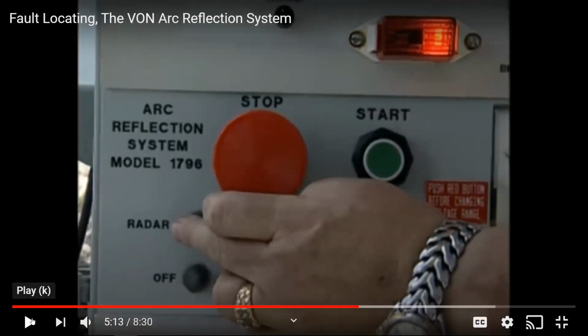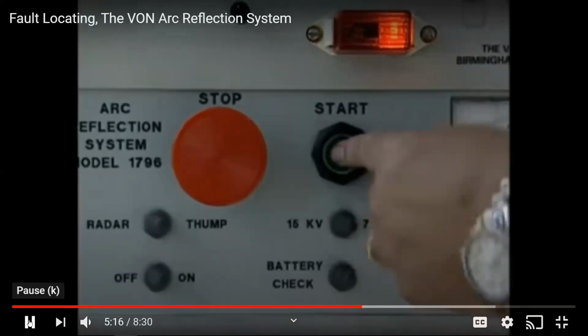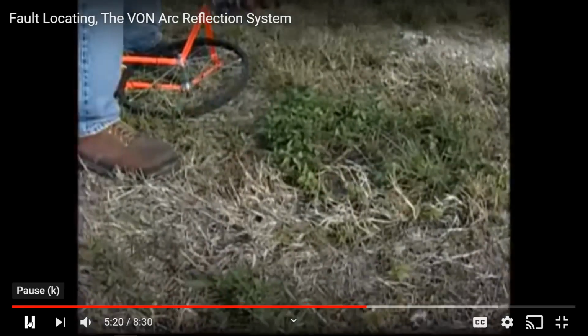Okay, now you go into thump mode. What it's going to do is charge up a capacitor inside the machine. And when the machine charges up, it's going to send a very high voltage DC current down the conductor. And presses the start button. The unit will then begin an auto thump sequence every 11 to 14 seconds.